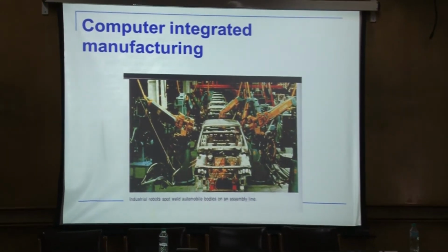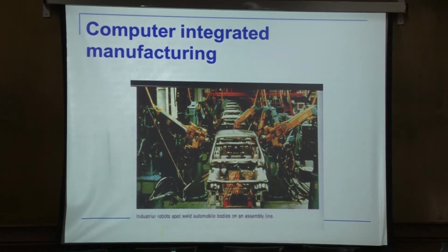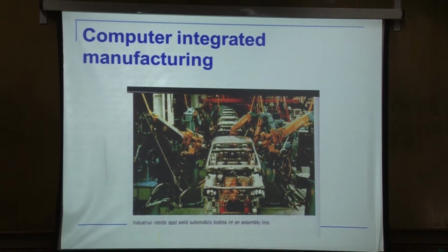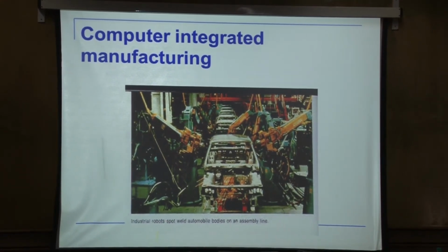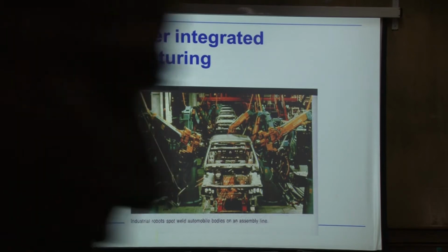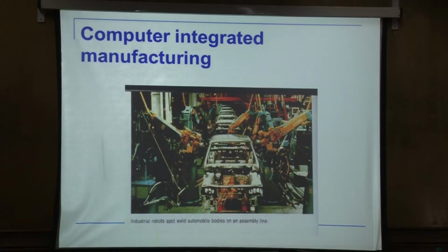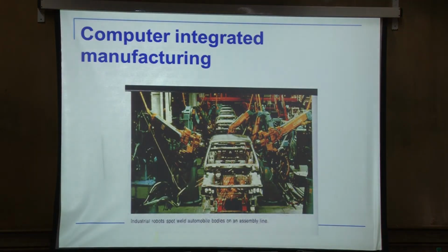Spray painting, spot welding, and assembly. These 2 tasks. Now, if you're trying to program this kind of a robot, although it appears that programming is very easy, well, actually it's not. Because if you try and program for this, not only must it get inside very complicated spaces, but it should also avoid hitting the object and not interfere with the other robots which are operating. And on top of that, your cycle time should be optimal. Because a little bit of delay also causes problems, it causes a lot of change over a large number of cycles. So this is the reason why robot programming is very, very specialized.